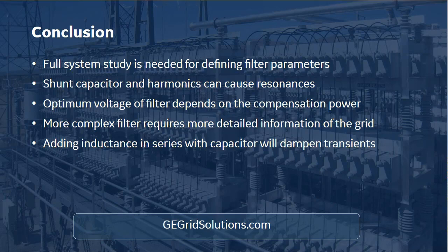Okay, so it can be done, I would say, if you have, let's say, 30 megawatts, when the range was 20 to 35 megawatts. If you have a 30 megawatt requirement, you want to have it in steps of 5 megawatts, I would divide it myself into one bank of 15 megawatts, one bank of 10 megawatts, and then one bank of 5 megawatts.